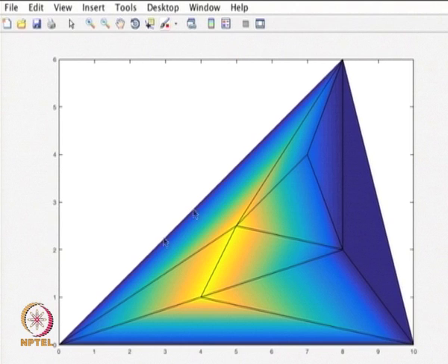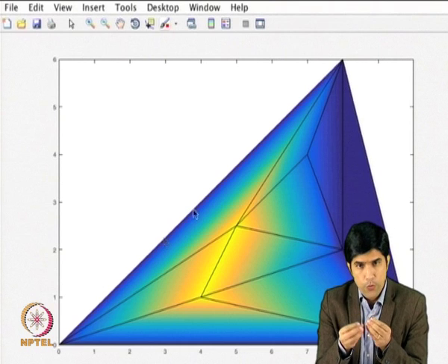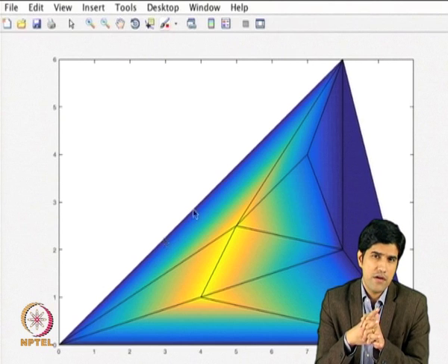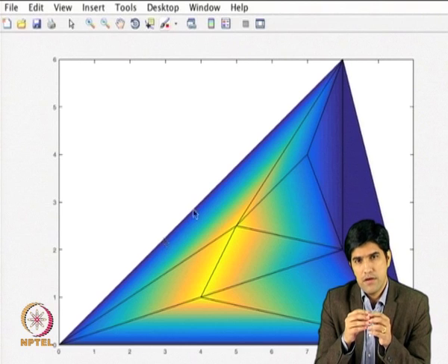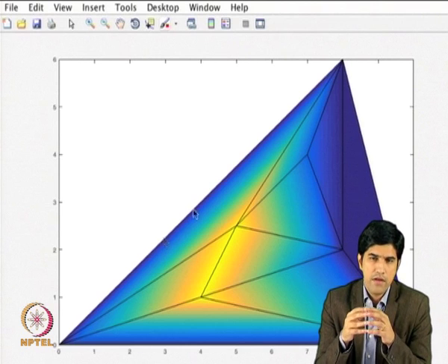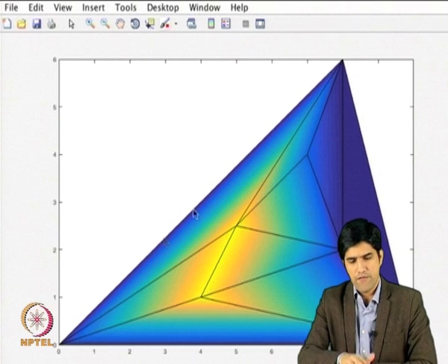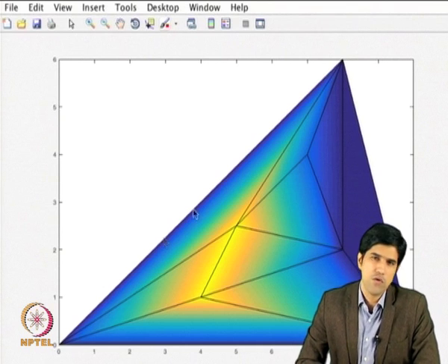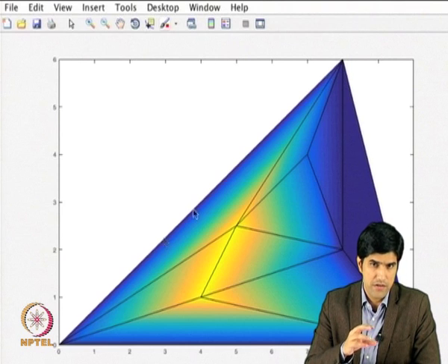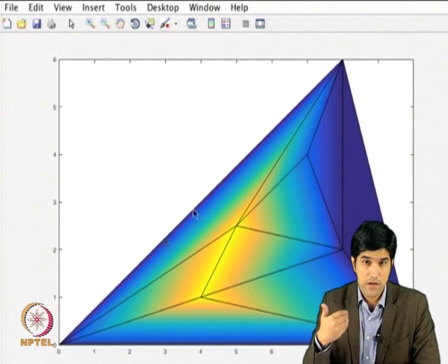So this is an excellent program for you to learn 2 things. One thing is how unstructured grids are used in the finite element method. So we have talked about the advantage of using an unstructured grid, the advantage of going to the finite element method, but we have not really covered the nitty-gritties of manipulating unstructured grids, managing the data and using those data in computation. So what I have tried to show is a very basic aspect of the unstructured grid. So you get to know what are the important parameters in the mesh that we are generating: the list of nodes, the list of elements, the connectivity of those elements, the boundary conditions, and so on.